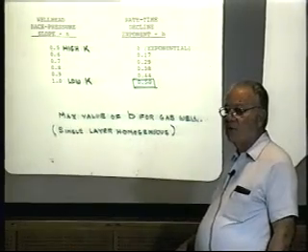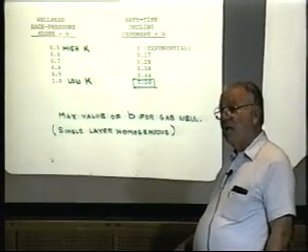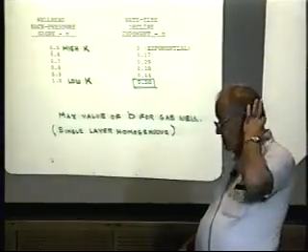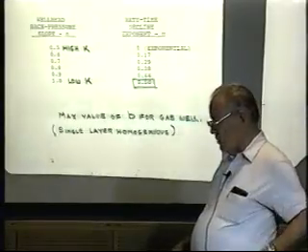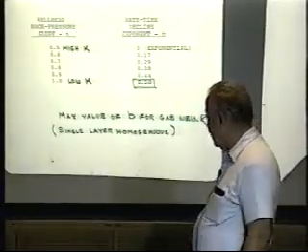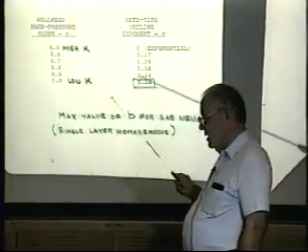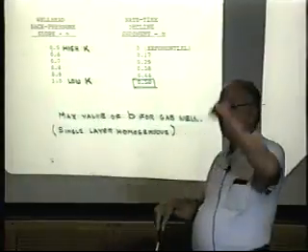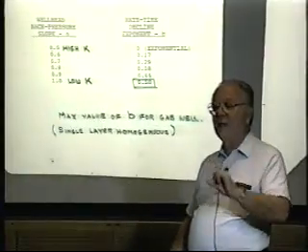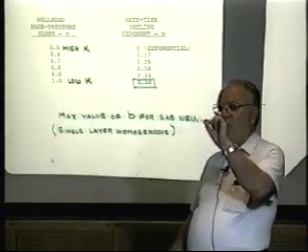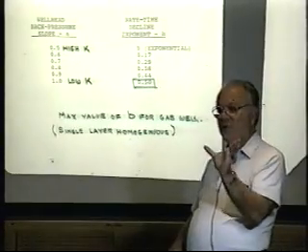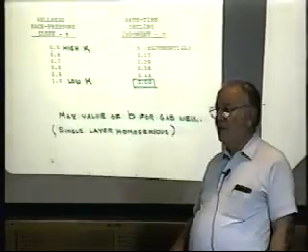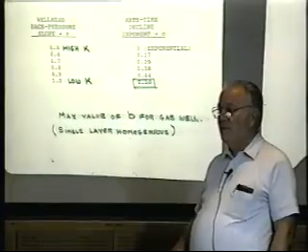There's an easy way also to calculate how long you can produce at constant rate before you go on decline. You just take the back pressure equation with a line pressure, and you go up the back pressure equation at the constant rate that you're going to produce. You get the shut-in pressure at which it's first going to go on decline. You go to your P over Z plot. You have to determine what the cumulative production would be over that period, and you divide that by the rate, and you get the time. And that's when you'd go on decline. You see that?